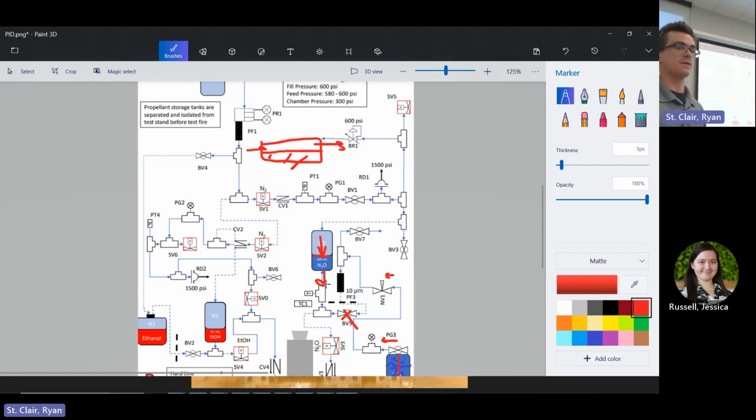Another important thing is why we stress having our propellants be liquid: you only get this blowdown effect if there's a liquid to be pushed down on. For example, if we were to use just nitrous oxide gas, that would mix with the nitrogen in the system, and you wouldn't get that blowdown effect. You would get a mixed effect, and your oxidizer would be a lot less potent.